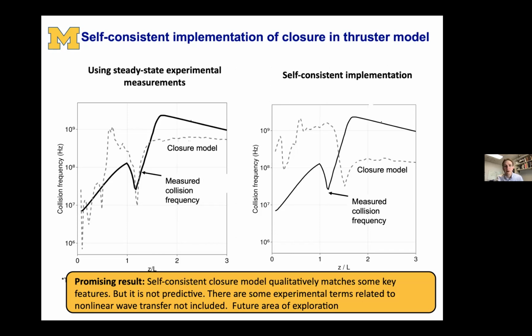But in terms of prediction, the gold standard for prediction for Hall thrusters is not the performance itself, it's the distribution of the plasma spatially. In particular, I don't have any profiles shown here, but we can measure experimentally how rapidly the ions accelerate and to what speeds. And the gold standard for evaluating Hall thruster predictive capability is how correctly you can capture that profile.